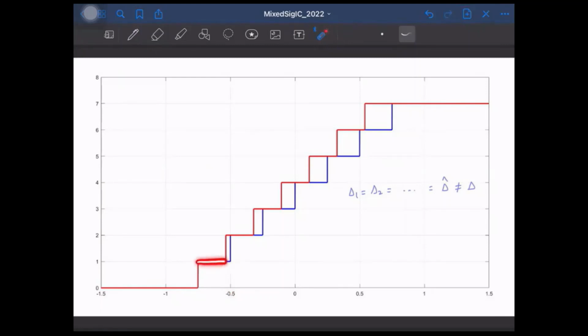It is smaller than the ideal value of delta. But the step size for all the codes is equal to this same value. Okay. So if you try to fit a straight line for the blue curve, you might get a line like this, right? Whereas for the red curve, you might get a straight line like this. Okay. So what has effectively changed is the slope of the characteristic, right? So this only results in a gain error.